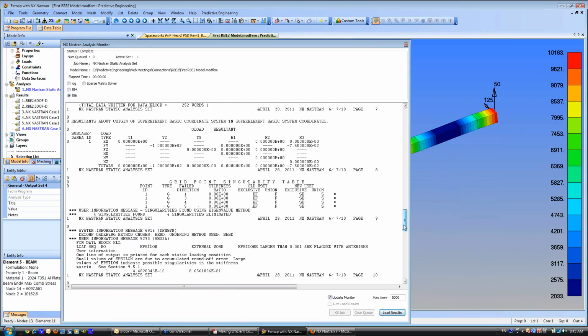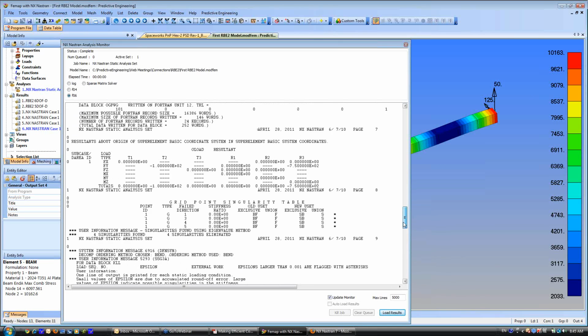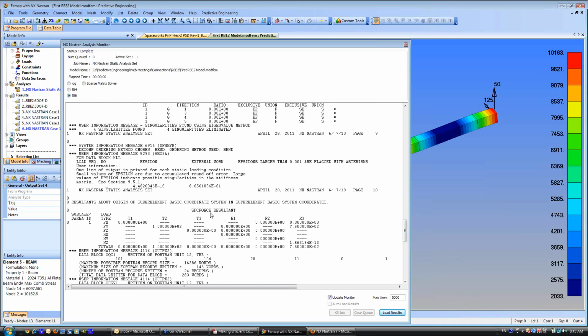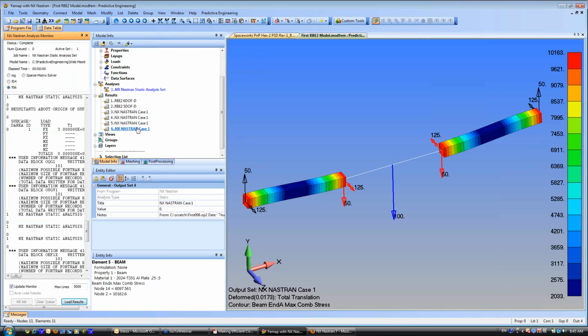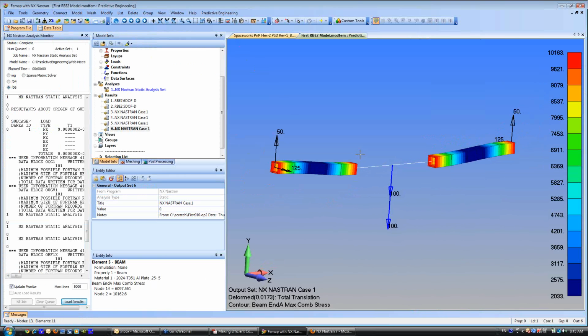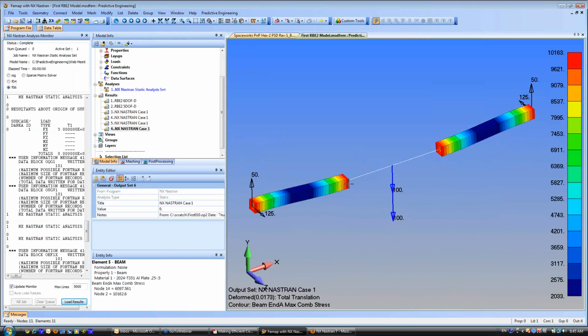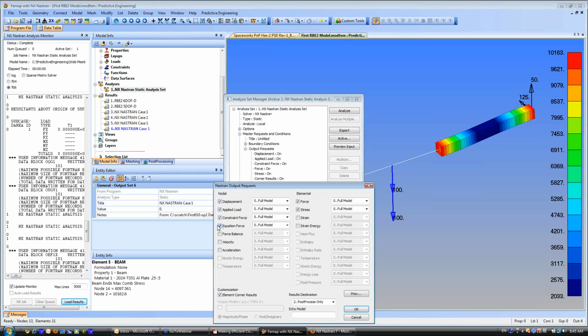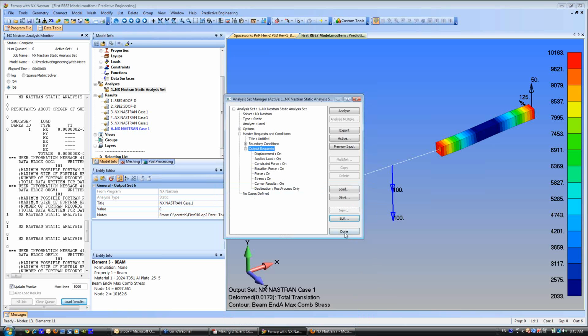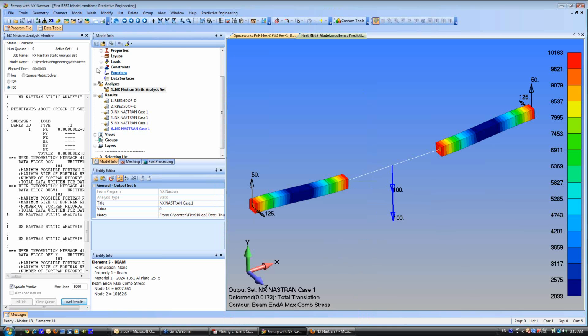So there what I did is I turned off equation, and you get the O load and you get the SPC force, but you do not get the multi-point force constraint calculated. That's empty. And in your free body diagram, there's no multi-point force to calculate. So let's go back to that, turn that back on. Fortunately, I only have to do this once for this seminar. Equation force. So that's going to calculate out your multi-point constraint forces.